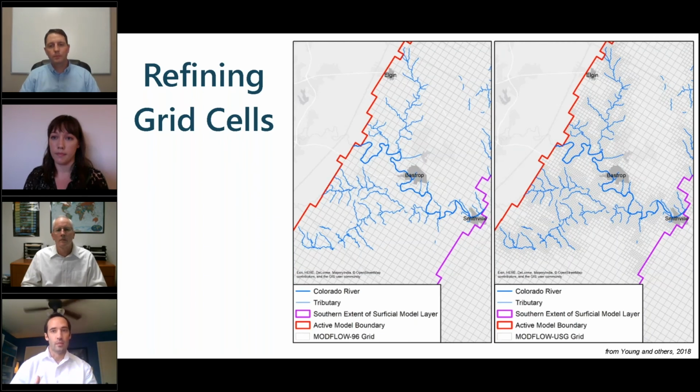So the more cells you have in a model, the greater the ability to vary those hydraulic properties and those stresses. If the cell size is too large, important features of the framework might be left out or poorly represented. With that said, if you go too fine, there are practical limits, which anybody that's worked with a model at 20, 30-hour runtime knows well doesn't usually work well. You pay the price for that computational burden in terms of the amount of time to complete the model and the project. So there's a sweet spot somewhere between too much and too little.